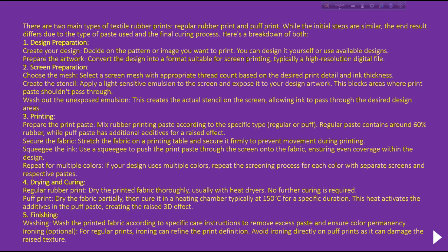Then create the stencil. Apply a light sensitive emulsion to the screen and expose it to your design artwork. This blocks areas where paste should not pass through. Wash out the unexposed emulsion. This creates the actual stencil on the screen, allowing ink to pass through the desired design.